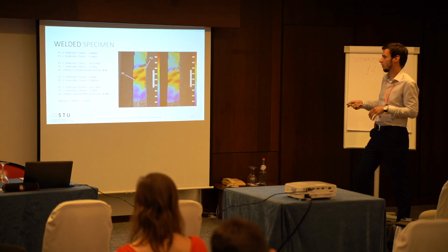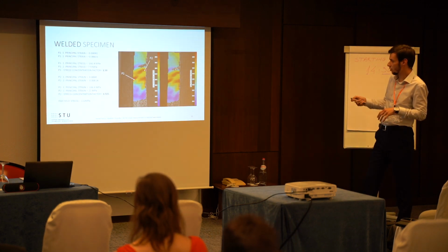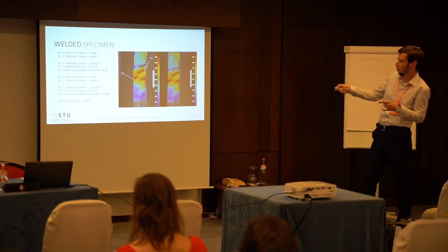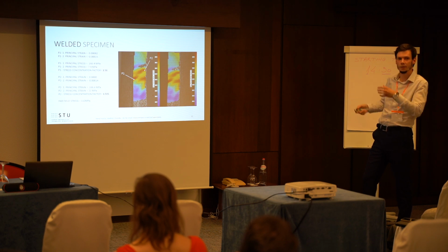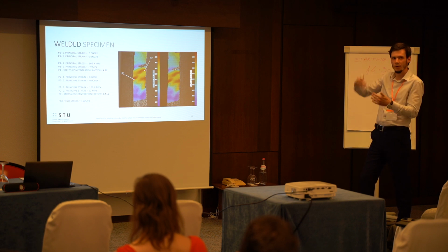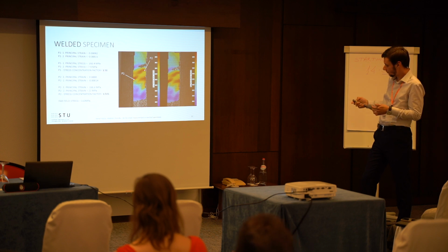Here we have some of the values. So we get some principal strains. We calculate the principal stresses for both of the points and get the stress concentration factors. These stress concentration factors are calculated from the component of the stress in the direction of the loading.